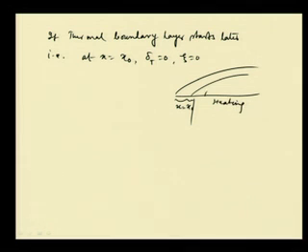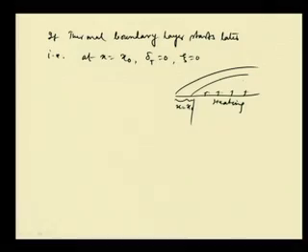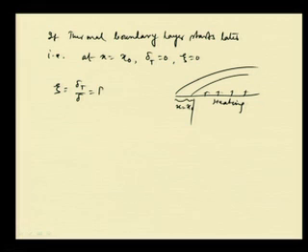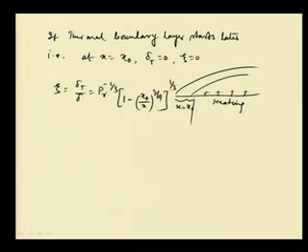There is a possibility, a case, of heat transfer from this point. So, the thermal boundary layer development is a little later than the development of the hydrodynamic boundary layer on the plate. Under that situation, this would be the boundary condition, and then we will have zeta equal to delta T. If we do the integrations properly, this becomes Prandtl to the power minus 1/3 into (1 minus (x naught by x) to the power 3 by 4) whole to the power 1 by 3.